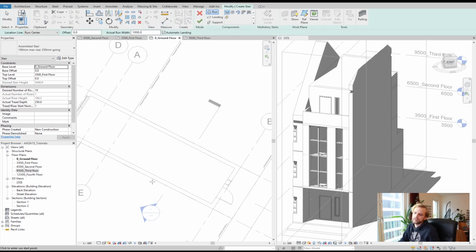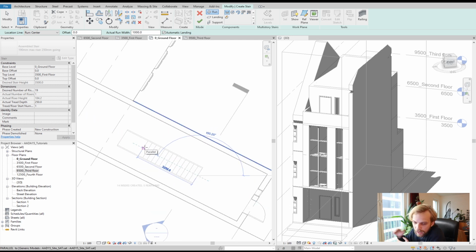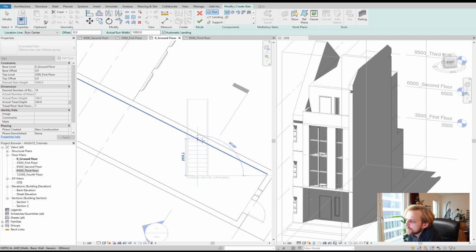And here is the stair creation tool, right? So I am able to either create a straight staircase, which is just straight up. And by the way, given the height of each step and the width of each step, it automatically knows how long the staircase is going to be.